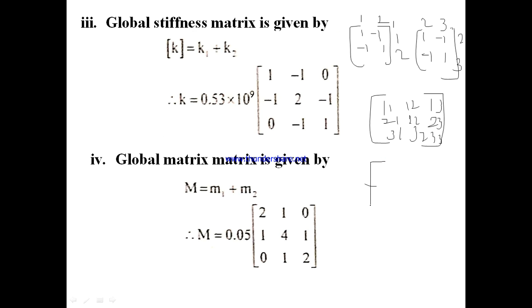So now the same way I need to carry out here. For 1 1, horizontally 1 and vertically 1, this becomes 1. Here 1 2, this becomes minus 1. Here 1 and 3, I don't have any connection between node 1 and node 3, so it will be 0. Same with 2 1, which is minus 1. Now observe carefully, 2 2 is a 1 here, and again here also I have a 2 2 with 1. So I need to add these two, and I will get 2.